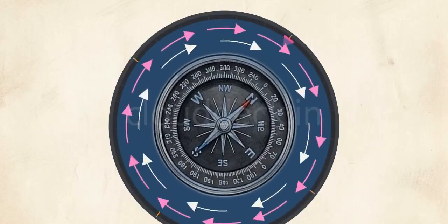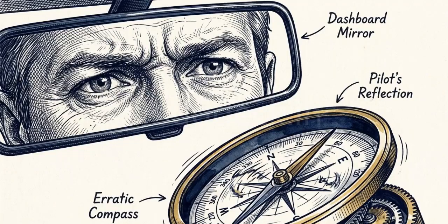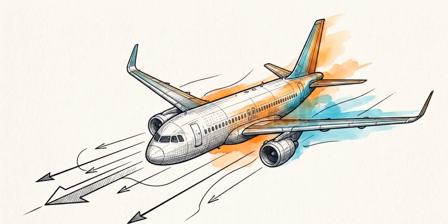This liquid swirl physically drags the card further out of alignment. Relying on the Earth's magnetic field forces pilots to use pendulous instruments that physically lie every time they change speed or alter bank angle. Once pointed on a heading, the fluid atmosphere asserts itself. Wind physically pushes the aircraft off its intended path,